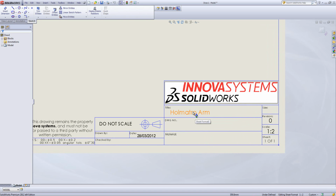And now I can just start editing some of these notes. So I've created a lot of properties earlier on, and within that part model I made up, I had properties within there. I also need to have properties within the drawing to link to those. So things like drawing number, I need a property to link to. We could just have a standard note, but obviously it's not going to update dynamically.